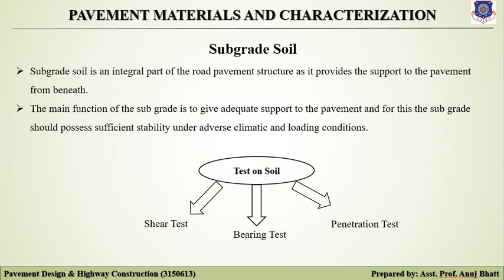Shear tests are usually carried out on relatively small soil samples in the laboratory. The bearing tests are loading tests carried out on the subgrade soil in situ, or on site, with a load bearing area. The results of the bearing test are influenced by variations in the soil particles within the stressed soil mass underneath, and hence the overall stability of the part of the soil stressed could be studied. The third is the penetration test.